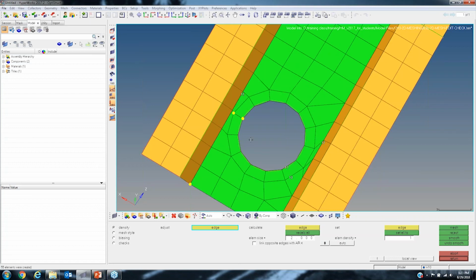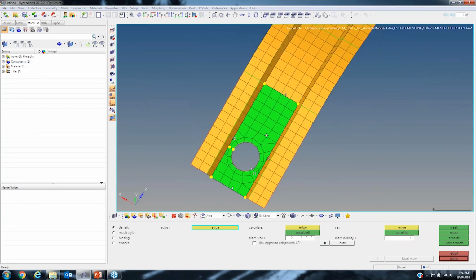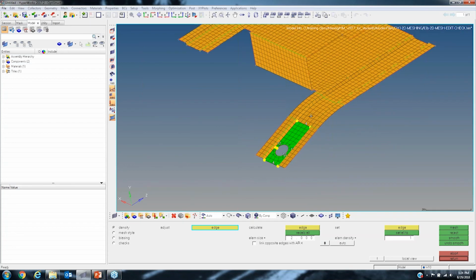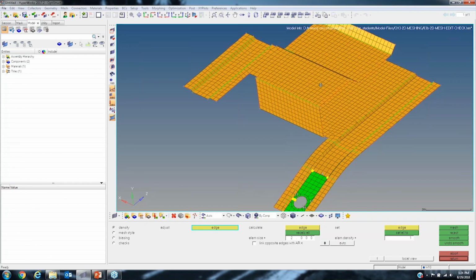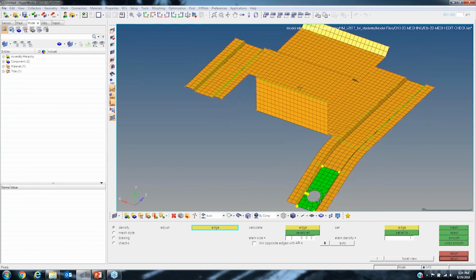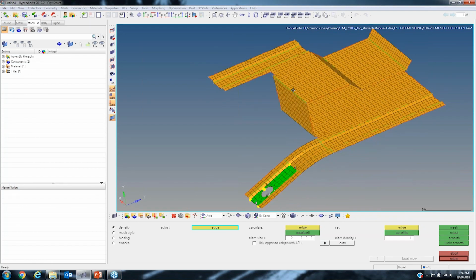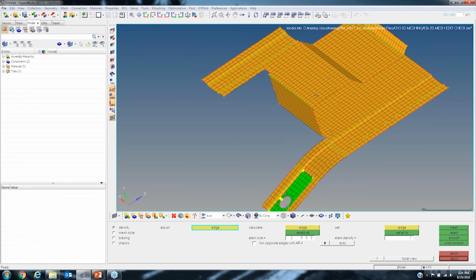And this will capture the stresses around, the bearing stresses around the actual holes, which helps you with your results later on. So this is a very useful way of editing your geometry. It's something that will help you guys a lot. So I recommend that you guys spend the time to use these edges to your advantage and generate a nice clean mesh. Just because at one point, some of these meshes will create a nice mesh that you can use later on to generate even nicer meshes further along the line, especially if you're working with 3D meshes or something like that.